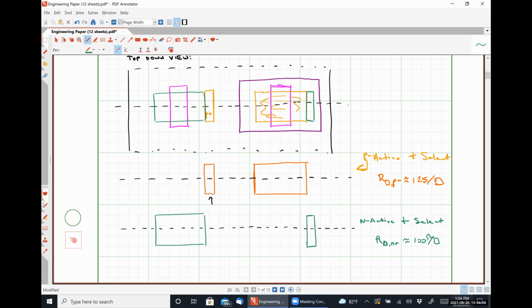But if you need a 50 ohm resistor in your circuit, you wouldn't want to use metal because it would take too much metal to hit that resistance. And I don't know that you could physically do it with poly or N-well, you'd have to make sure that the current flows through it in an oblong direction or something like that. So this is how you get those kind of intermediate values, so not on the order of ohms, but not up to kilo ohms yet either.